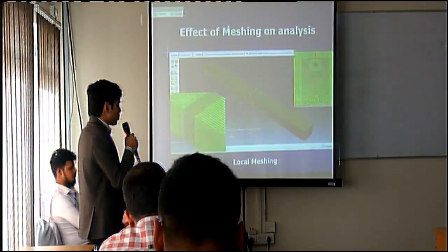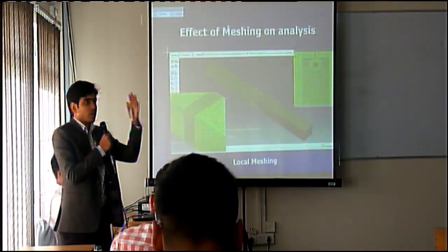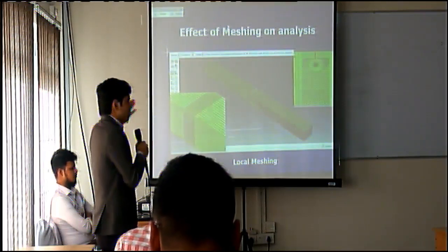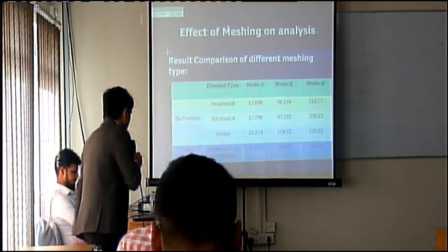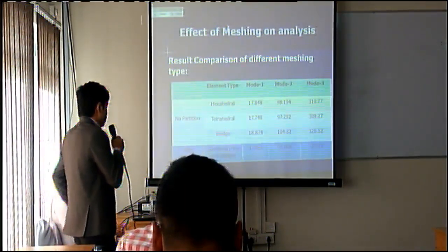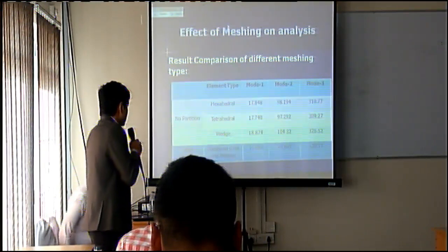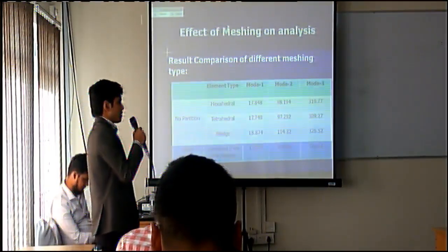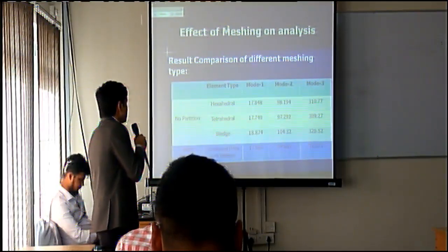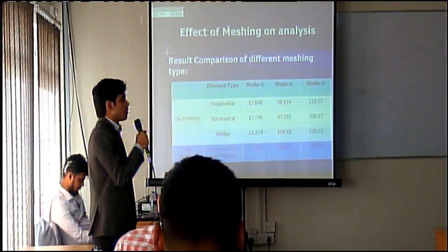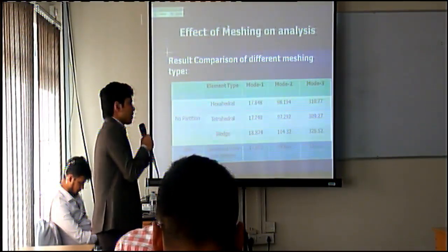At the tip of the crack I have used wedge element, and for regions further from the crack I have used hexahedral element. And the result shows that if we use combined hexahedral and wedge element, the frequency reduces much. That is compatible with the experimental available result, that the frequency reduces when crack is present.